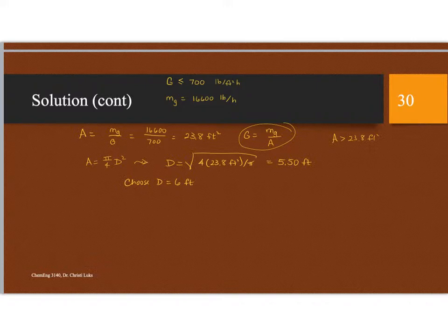So now, how do we determine the dryer length? To do this, we need to find a formula from literature, or in this case our textbook, for this type of dryer. So for an adiabatic rotary dryer, we've got an equation. Our formula says that the length is equal to 8 times the heat duty Q over pi diameter G to the 0.67 and delta T, and this is the log mean temperature difference.